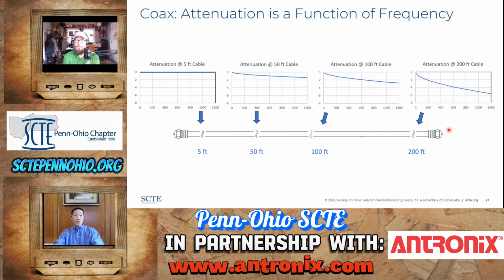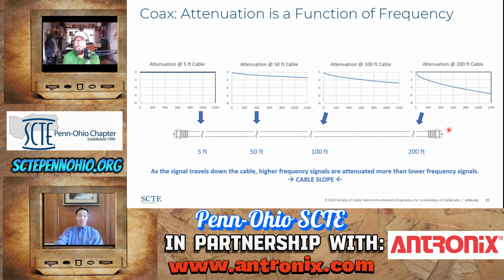What we call this is, as the signal travels down the cable, the higher frequencies are attenuated more than lower frequencies. And this is the cable slope. As there's more cable in the network, this is the type of slope you'll see as the signal travels down the cable. I think it's important to note that coaxial attenuation is not perfectly linear, right? It has a little bit of shape to it. Correct. And we talked about shape earlier, and it is important.